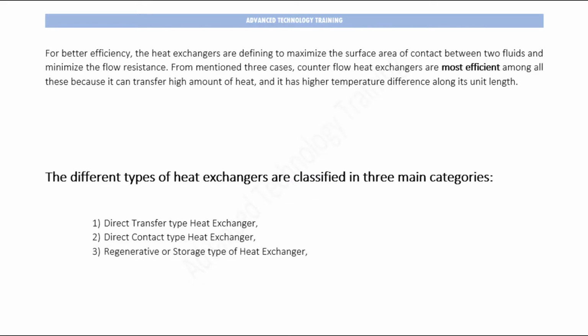For better efficiency, the heat exchangers are designed to maximize the surface area of contact between two fluids and minimize the flow resistance. From the mentioned three cases, counterflow heat exchangers are most efficient among all these because they can transfer a high amount of heat, and they have higher temperature difference along the unit length.